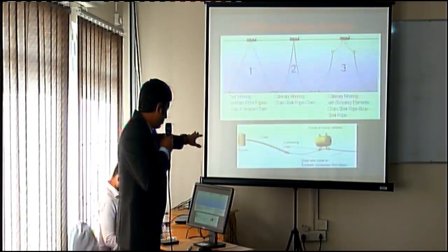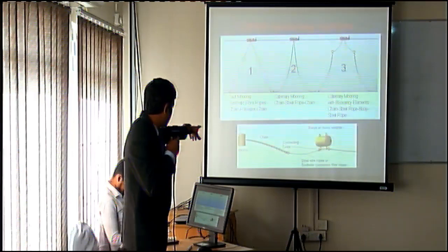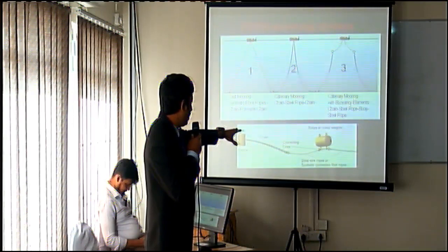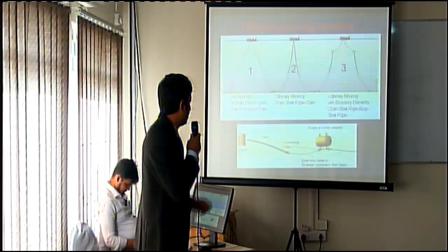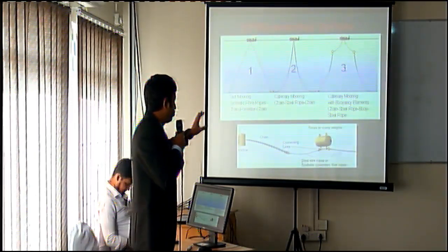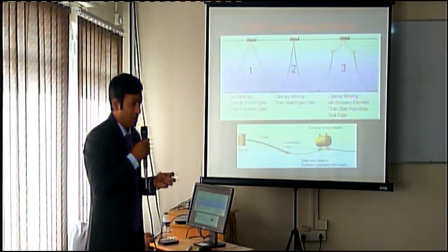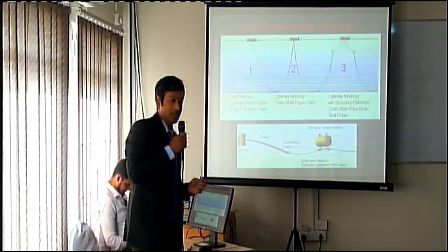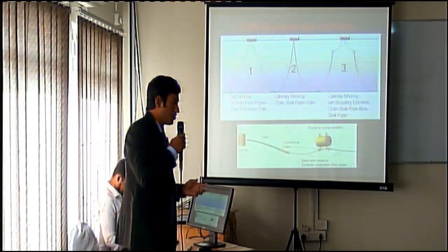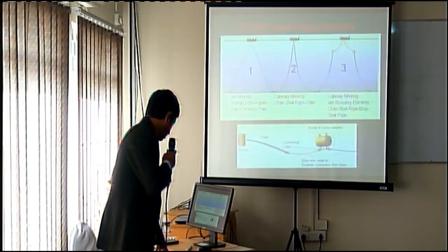In the figure below, you can see that the mooring line starts from the anchor, and then you have the chain, a connecting link, and then the steel wire rope. If you have a buoy on the mooring line, you can attach it, and later we will have chain again. So what we are trying to do is the fatigue analysis of this chain, because it will experience a lot of cyclic load, and that's the problem for it. It will experience fatigue damage throughout its lifetime. So we need to analyze it, but we'll try to do it in a simplified way.